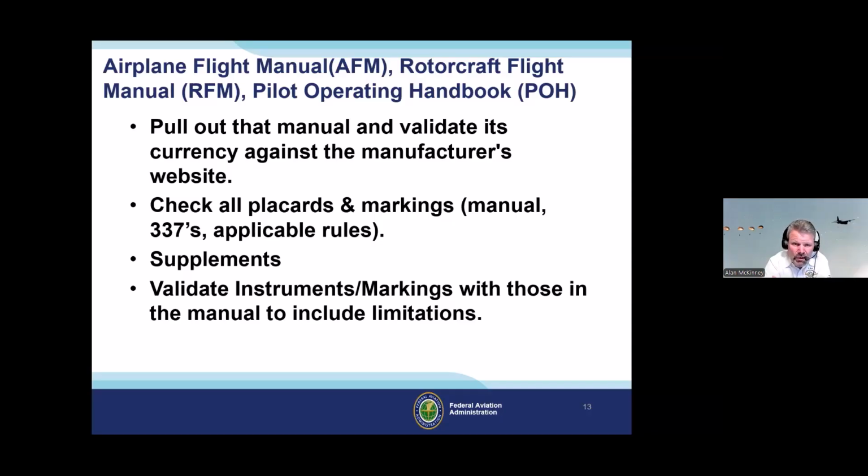But you do want to make sure that whichever flight manual or flight manual supplement, if it's an STC, is accurate for your installation, right? So that's what you want to make sure. Use the flight manual to check placards and markings.